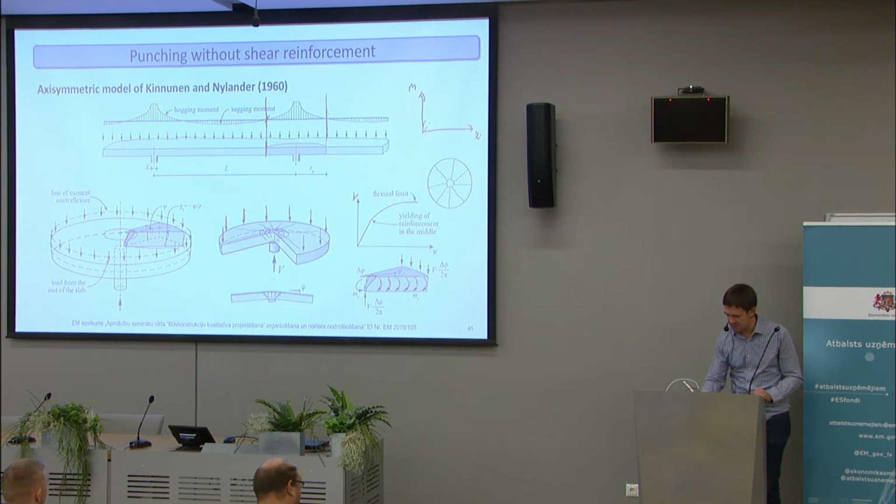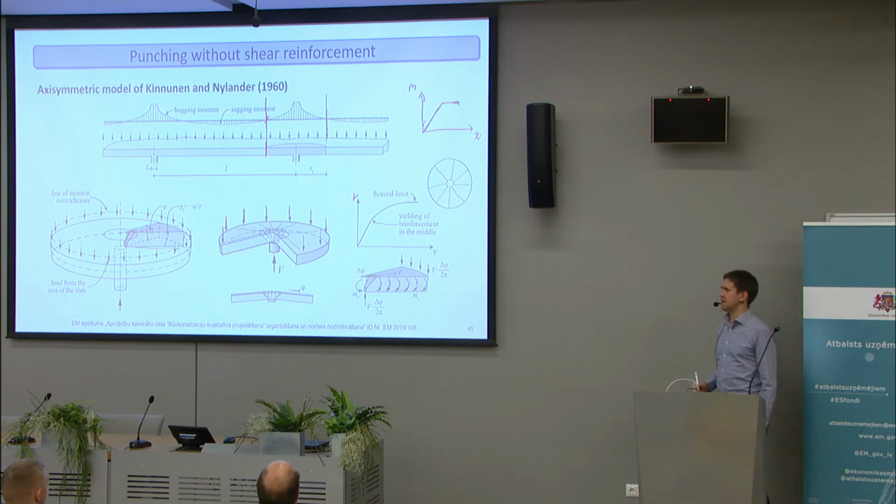They actually used the simpler bilinear relationship, so they don't take into account the contribution of uncracked concrete, and they only look at the situation after cracking.